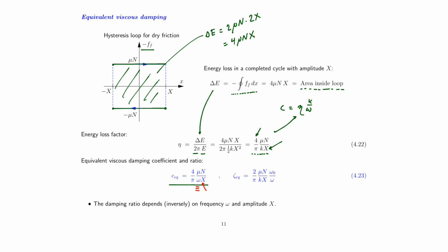And this is kind of the hen and the egg problem, namely that the amplitude depends on the amount of damping, but in this case the amount of damping also depends on the amplitude. So it needs some kind of trial and error, iterative process to actually come up with a good guess for this viscous coefficient. In many cases, it's time consuming to make simulations with pure friction.